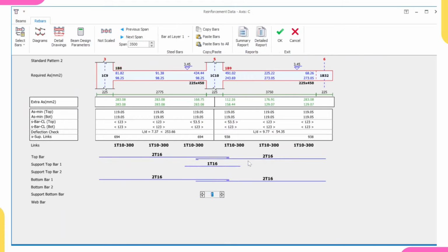So what I'm having here in total is 3Y16, because this is 2Y16. So 2Y16 is passing here, then plus this one is still 3Y16, so it will stay the same thing. But if you arrange it like this, your detailed drawing arrangement will be more accurate.